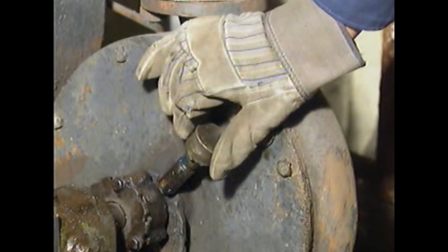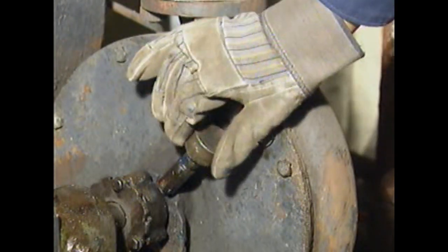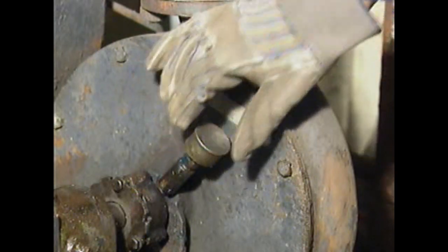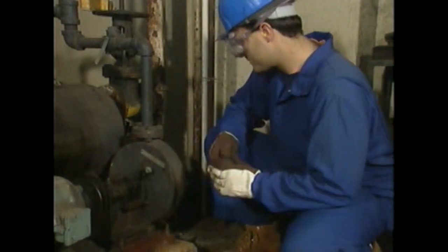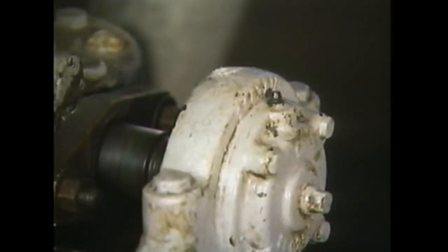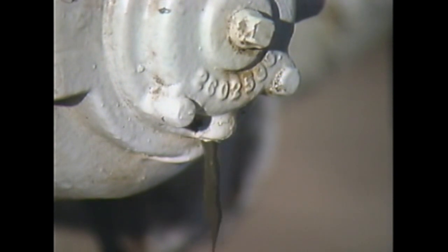Sometimes workers apply grease to operating equipment by turning a screw-type cup to force grease into a component such as a bearing. The level of grease in the cup must be checked regularly. If the level is low, the cup must be refilled. Anti-friction bearings often have housings that retain grease and help keep out dirt. But a problem can occur if too much grease is put into the bearing because there's no place for the excess grease to go. Consequently, a way for old grease to leave the bearing must be provided.